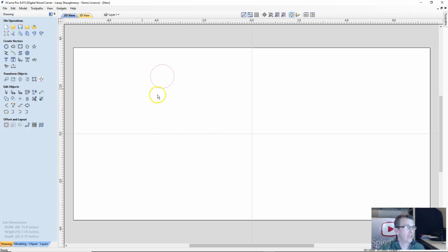If we were looking at the shape itself, if we went into the node editing of this, you would see these nodes, these points. And these points are determining the path of the lines, in this case the arcs in between each of the two nodes, to create our complete circle. Now, we have these indicators, these clear nodes here.